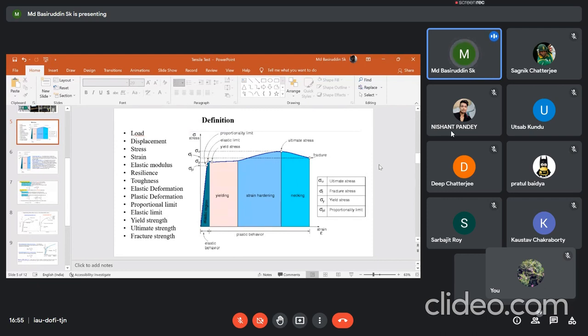Okay, when necking starts, what are the things that actually change during straining? The cross-sectional area reduces. Cross-sectional area reduction generally happens, right? So can we think that we can correlate the strain irrespective of gauge length?